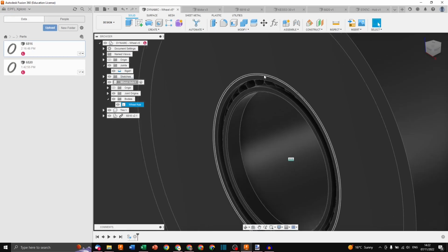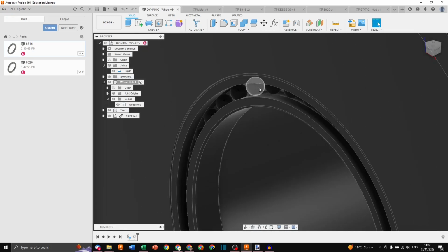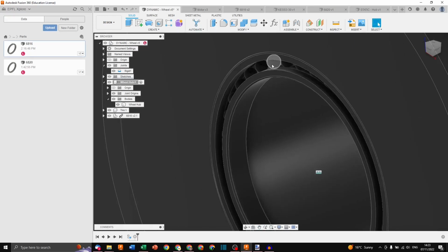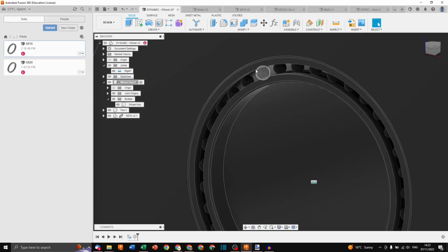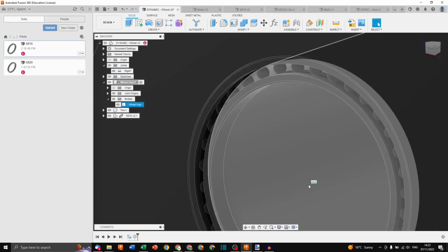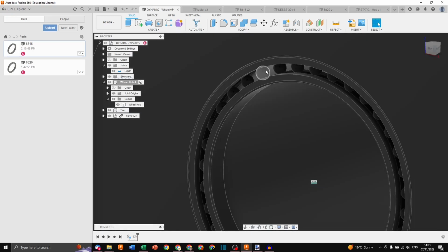I would also need to add a rotating joint between the ball and both the outer and inner race, but it's not just rotating. The balls are rotating on themselves around this main center point. So it's sort of like a planetary joint that's moving like this.